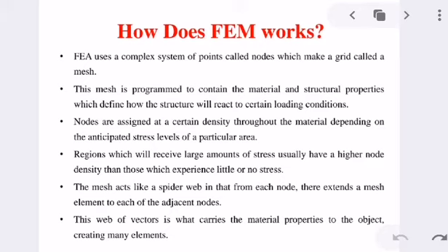In the finite element method, the solution region is regarded to be composed of many small interconnected subregions called finite elements. Within each element, a feasible displacement interpolation function is assumed.